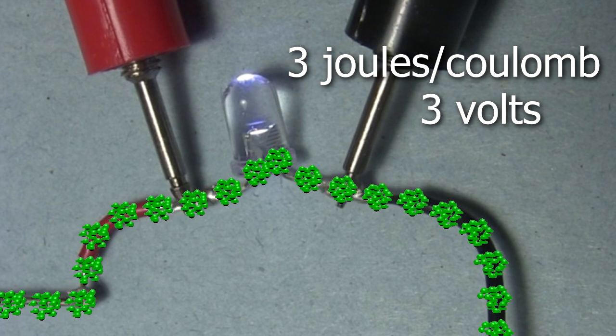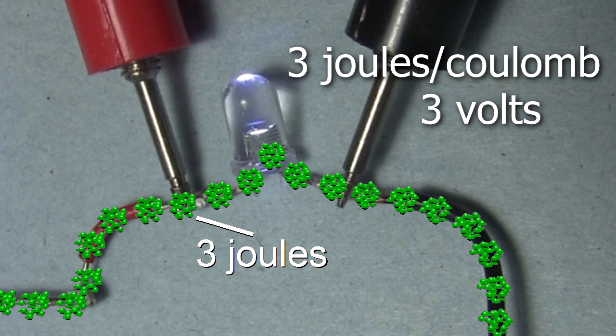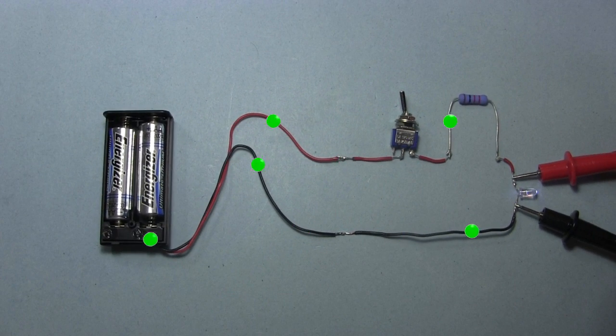Now let's increase the amount of charge moving from here to here, but the voltage is still just 3 joules per coulomb. 3 for this coulomb, 3 for this one, and so on. There's a lot more total energy this time, but the voltage is no higher. It's still just 3 joules per coulomb, 3 volts. And that's what voltage is when talking about charge moving through a circuit like this.